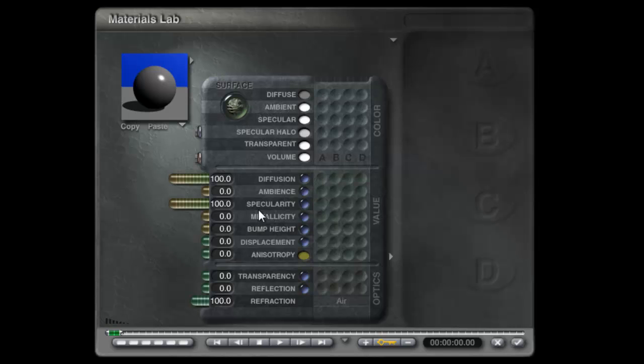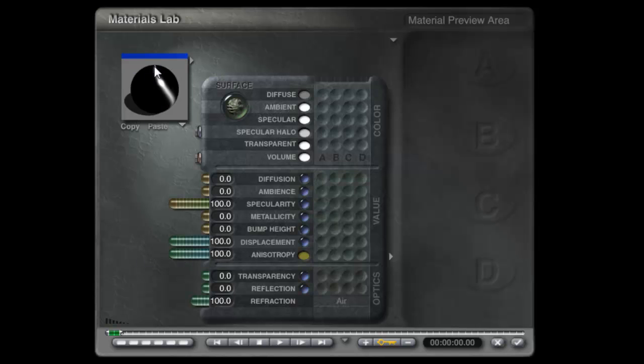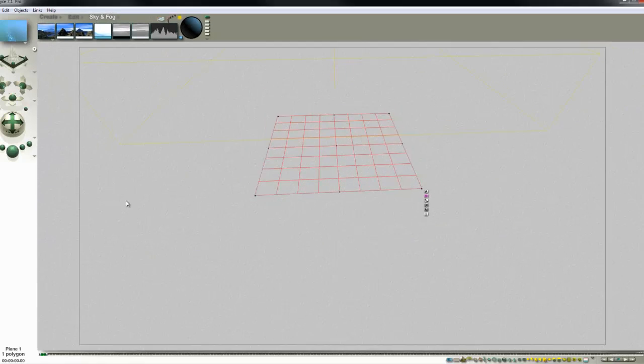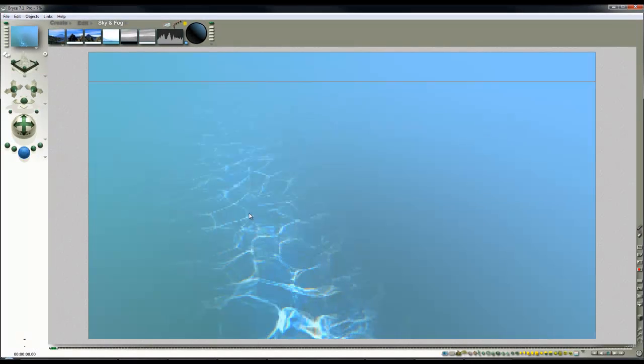What I'm going to do is turn the specularity up to 100, turn the diffuse right off, so we're only looking at this specular effect, and then turn anisotropy up. You can see how it spreads the specular halo across the surface. And because the gel also has a specular output, that now illuminates this area. So that's the specular response from the light source that we've added to the scene.